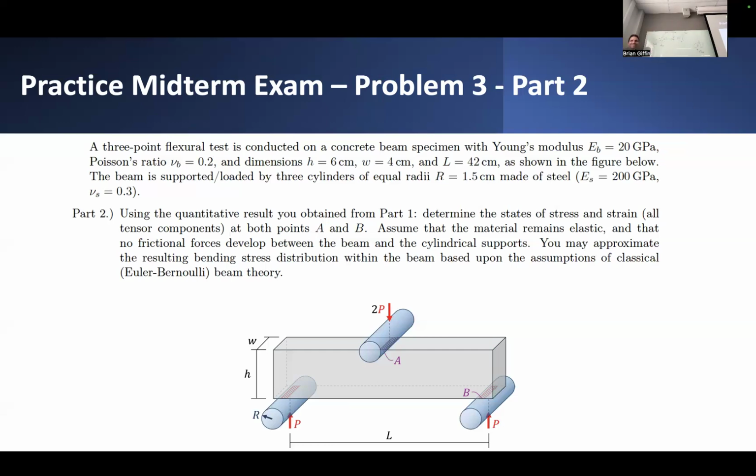So sigma XX, that's the thing. How do we characterize sigma XX, sigma ZZ, and all the other shear components of traction or stress defined at this particular block point? To determine all these things, we can use boundary conditions, in the same way that we determined the vertical component of stress acting on the top of this block. We said that there's a contact pressure there. It's compressive, it's pushing down on the top of the block. But remember, with boundary conditions, what you see is just as important as what you don't see.